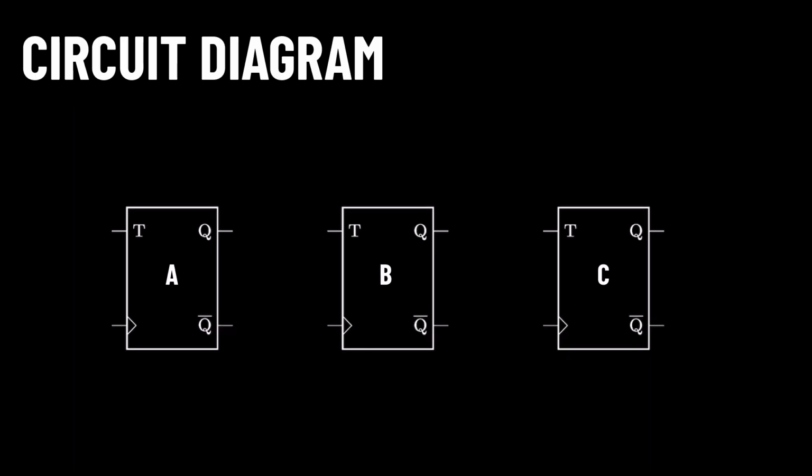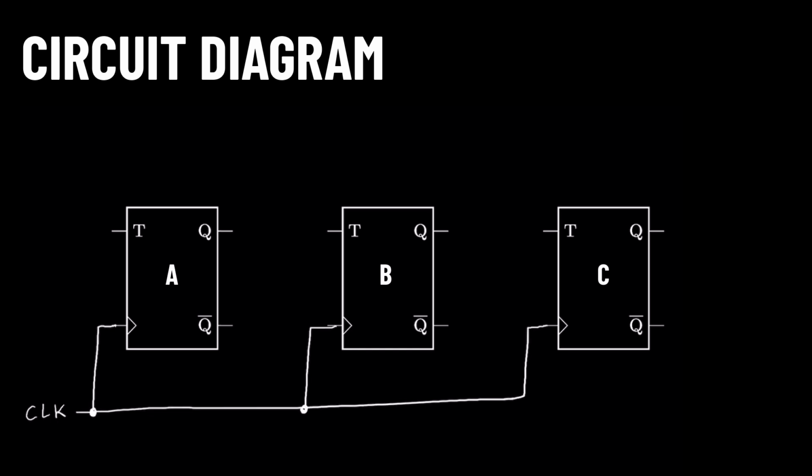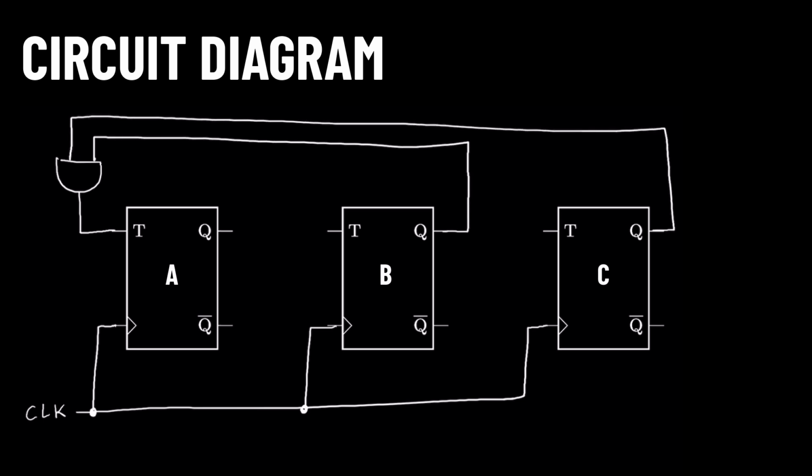How do we wire this up? This circuit is fully autonomous and requires no input values from us whatsoever, so there will be no dip switches or push buttons. The 3 flip-flops all share a common clock signal. The input to flip-flop A is the AND of the outputs of flip-flops B and C. The input to flip-flop B is the output of flip-flop C. The input to flip-flop C is VCC.